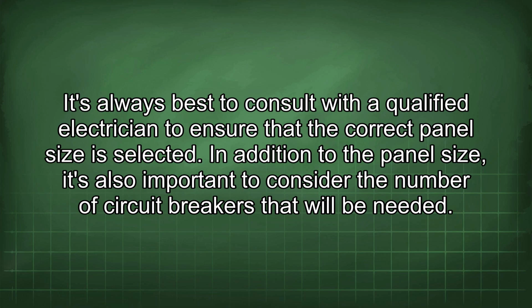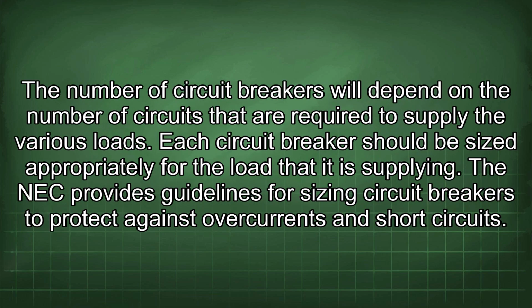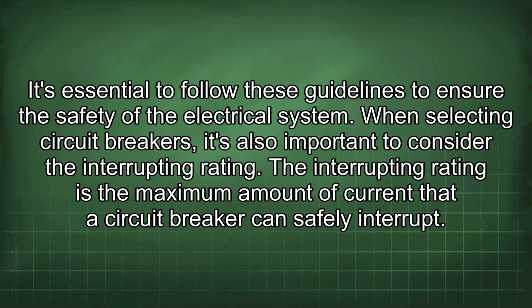In addition to the panel size, it's also important to consider the number of circuit breakers that will be needed. The number of circuit breakers will depend on the number of circuits that are required to supply the various loads. Each circuit breaker should be sized appropriately for the load that it is supplying. The NEC provides guidelines for sizing circuit breakers to protect against overcurrents and short circuits. It's essential to follow these guidelines to ensure the safety of the electrical system.